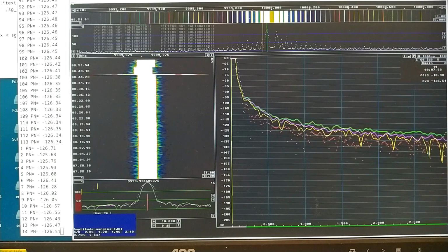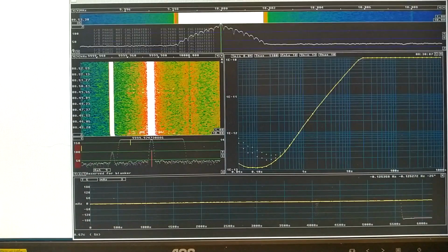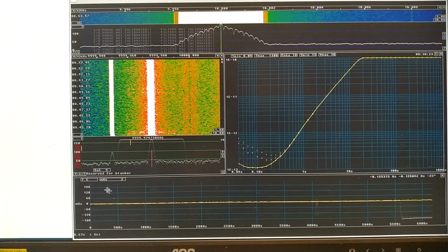The difference is about 30 millihertz, and I have had the Allan deviation graph running on the same signal, and here the frequency scale tells me it is minus 182 millihertz or something like that. Obviously, I have made an error in the frequency scale. I will have to correct someday.